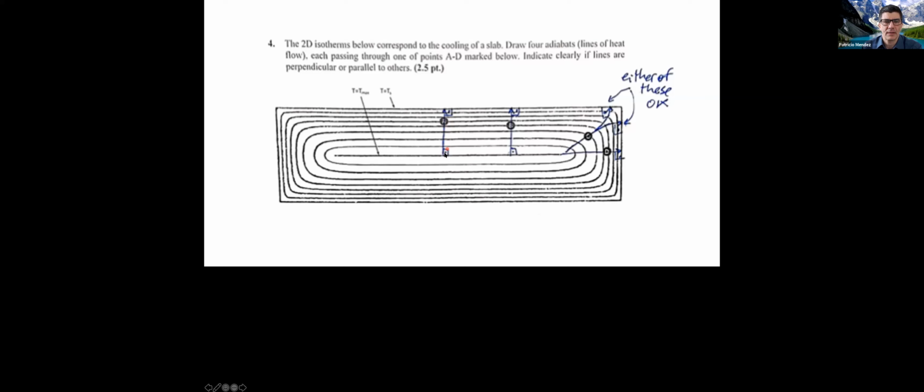If I'm assuming that the center is the maximum temperature, and this is moving out. So for those of you in MADI, this is the temperature distribution from continuous casting, during cooling in continuous casting of steel or aluminum. Actually, I got this image from a paper. So here we get to see these isotherms. We would make an adiabat that looks very much similar.